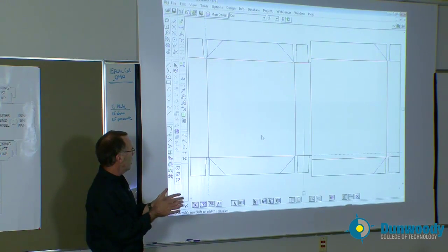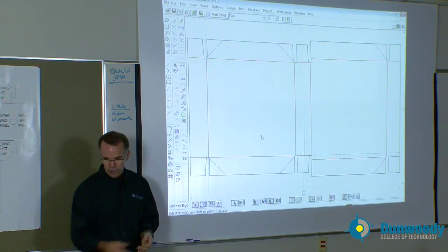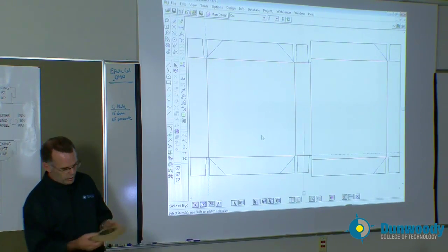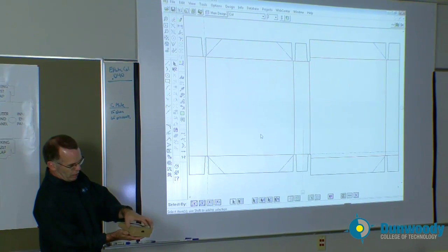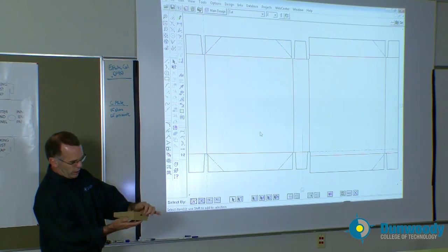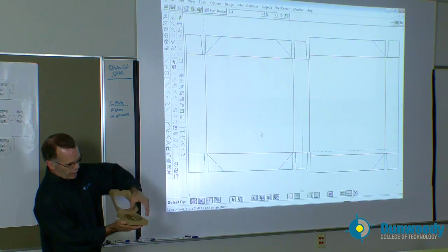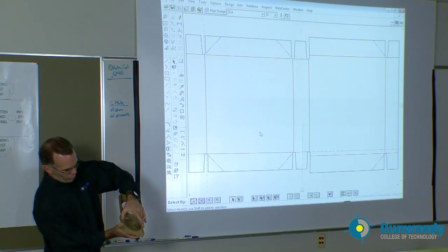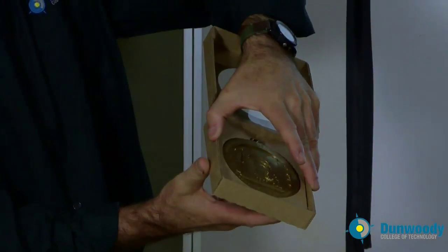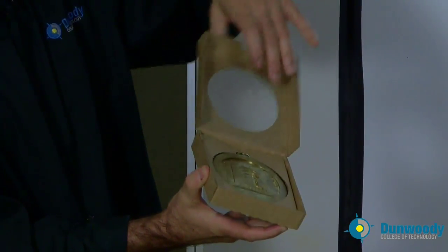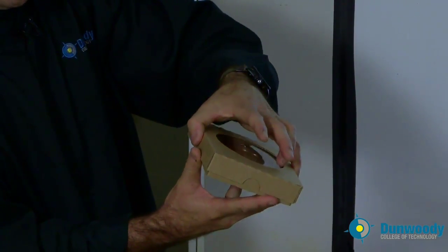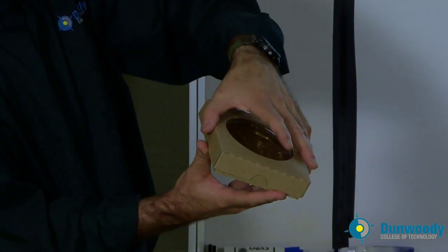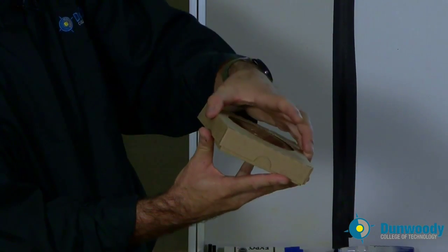He also has to make minor modifications because in something like a tray right here, this surface actually has to be expanded a little bit because it's got to come outside of the walls of the bottom section right here. So the top section and the bottom section can't be equal to each other. The lid has to be ever so slightly bigger in both directions to make sure that this thing opens and shuts.